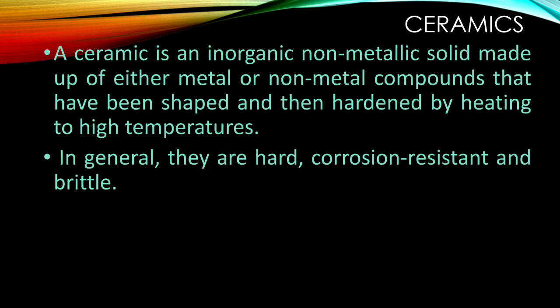And we also discussed thermosets and thermoplastics. Thermoplastics can be melted and recycled, and melted again and again. Nothing will happen. It's a simple linear structure. A thermoset, once it is set, cannot be remelted or reused. If you supply heat to try to melt the material, it will simply degrade.